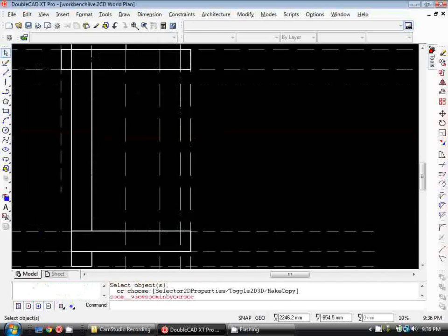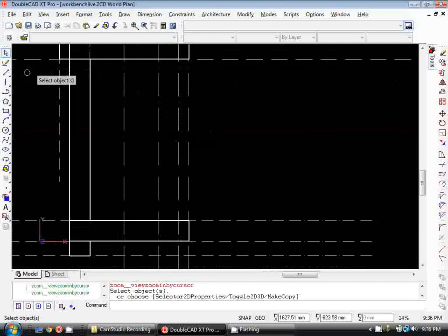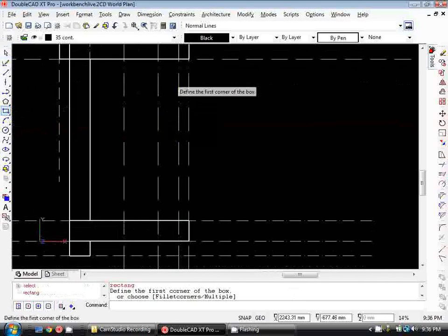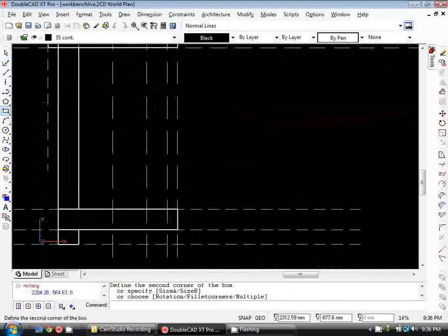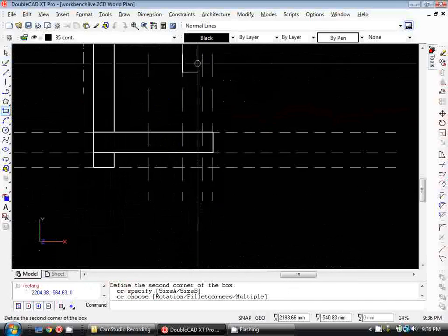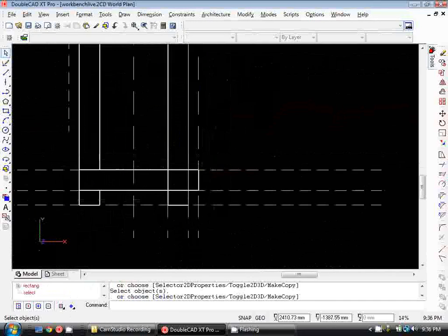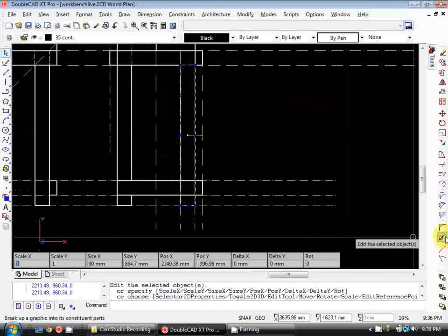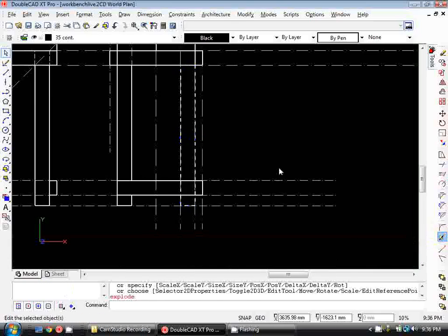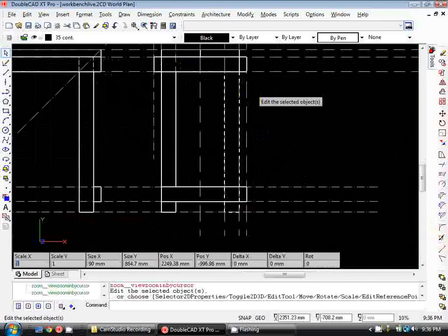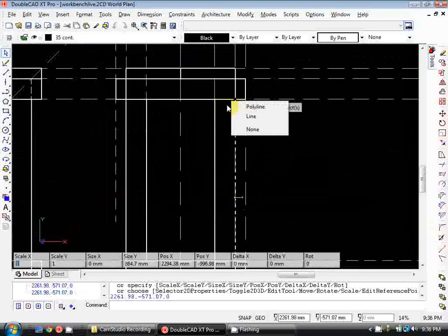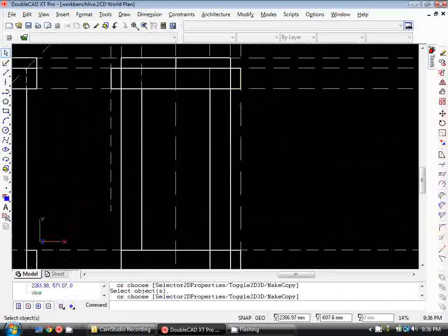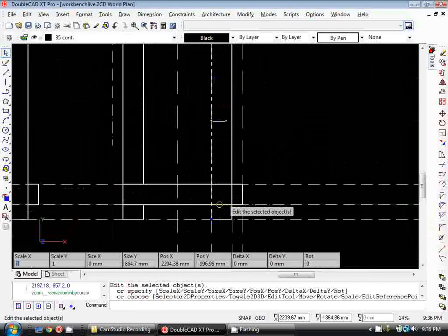I'll show you the break tool as well. So I'm going to just draw this leg as one rectangle. So if I click on that point and then the bottom point here, now you'll see that this is all treated as one object. Now over on the side here I've got the explode tool. Now what that does, when I click that, it separates this rectangle into its individual lines. So I can delete that top line. So I've got a bunch of lines here.